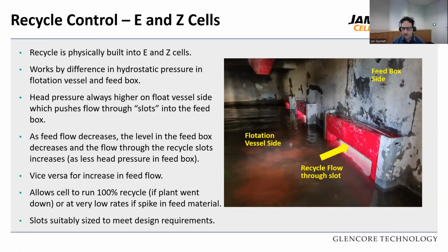One of the things that's actually quite interesting is it allows you to run your cell on 100% recycle if your plant went down, which is quite useful in other applications. Say if you're starting your circuit, you can start them up on water, run them on 100% recycle, and then start to add slurry in a more controlled way. And like I said, the slots are suitably designed to meet the requirements of the cell sizing.